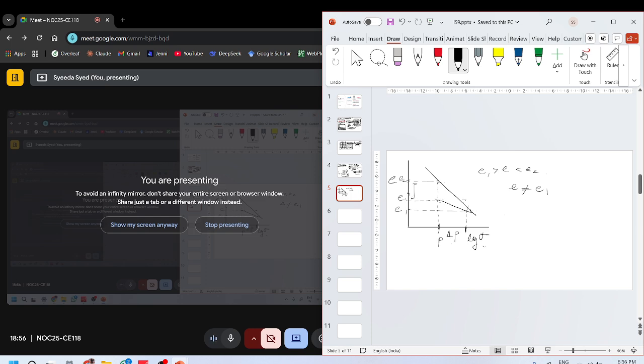This is the part of deformation that I got back. So this is the elastic part. This is the plastic part. So when you are talking about the soil analogy, this is elastoplastic, but this is only elastic because you are recovering back your elastic strains.